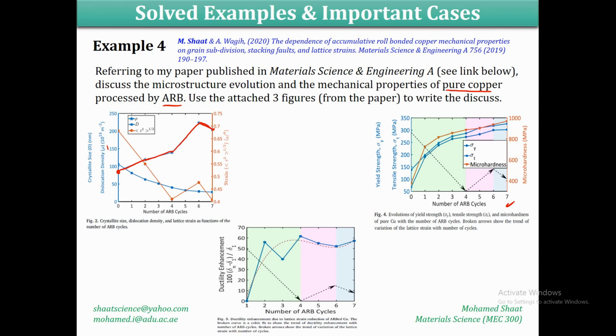So this is going to give us at the end 10 to the power 7. So it is going to be around 80. In total, it's going to be around 8 times 10 to the power 8 as a dislocation density, millimeter to the power -2. This is the dislocation density of the pure copper before rolling.